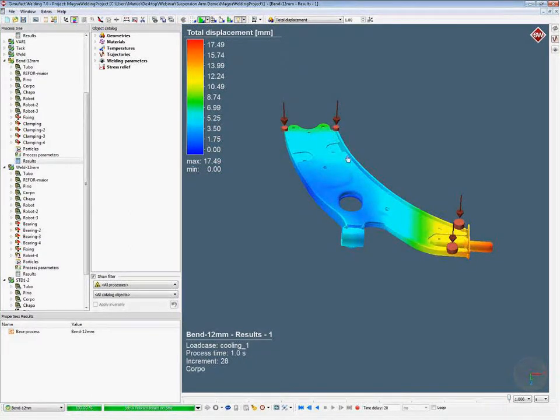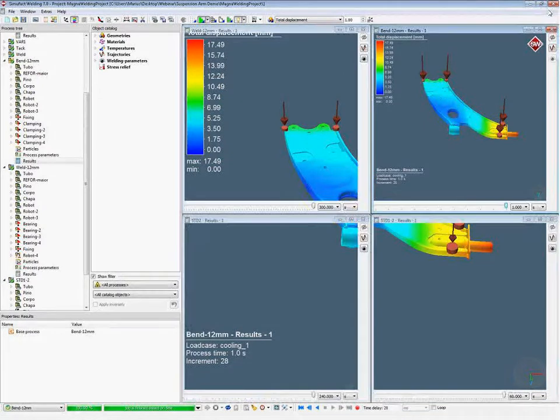Because behind this, if we then weld along this line, shrinkage due to the shrinkage of the weld seam will then increase distortion in -z direction upward, and then we will end up with a fine distortion distribution.